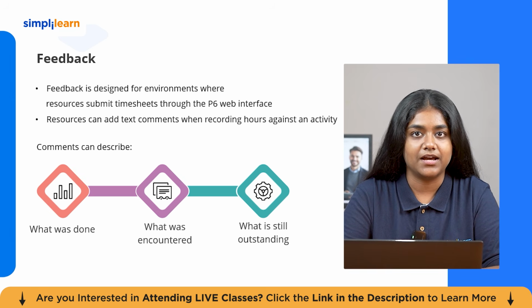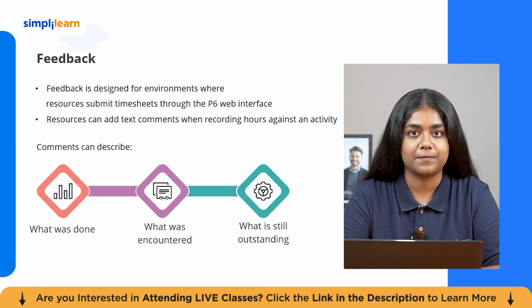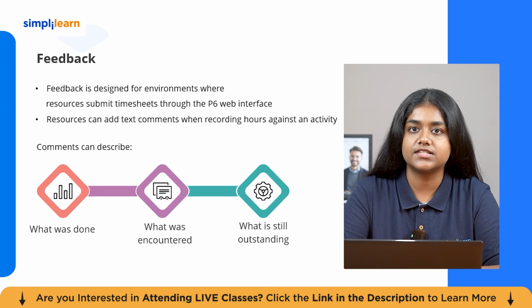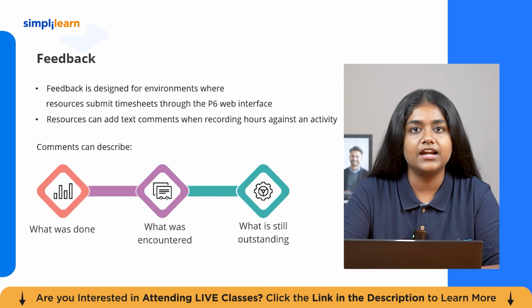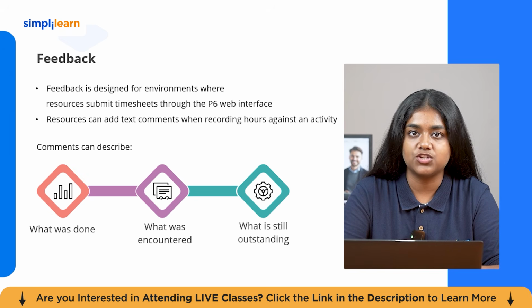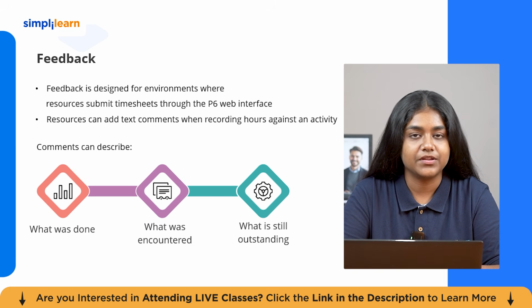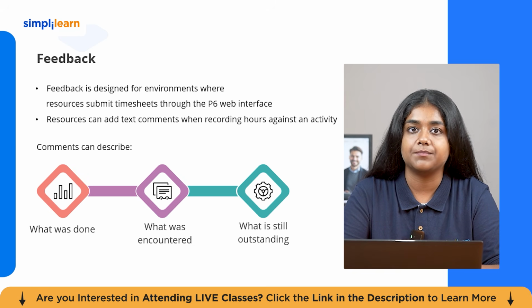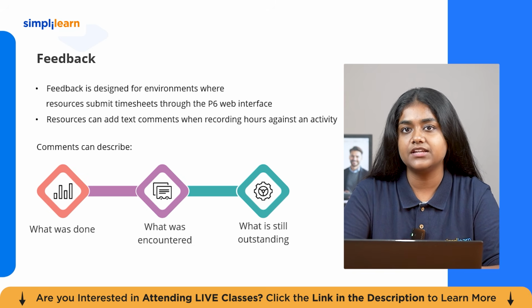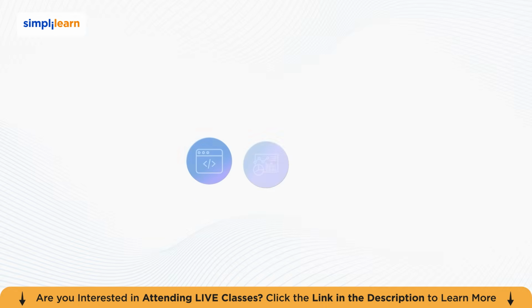So let's understand about feedback. Feedback is a feature specially designed for environments where resources submit timesheets through the P6 web interface. When a resource records their hours against an activity, they can add a text comment describing what was done, what was encountered, or what is still outstanding. This feedback is visible to the project manager alongside the timesheet data, giving qualitative context to the quantitative hours. For large projects with many resources submitting timesheets remotely, feedback significantly improves the quality of the progress information reaching the project controls team.